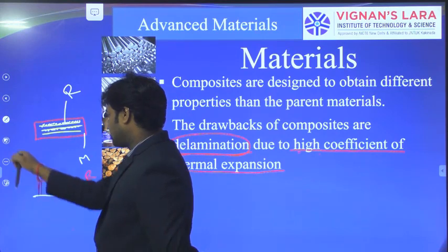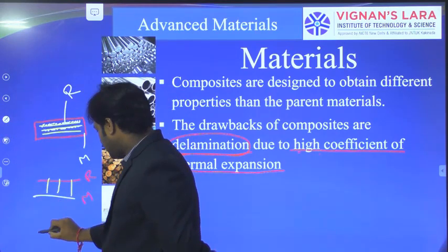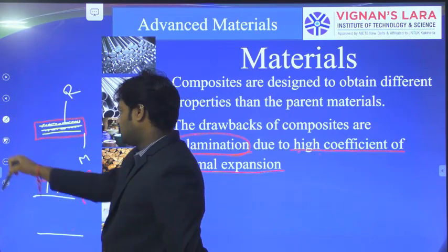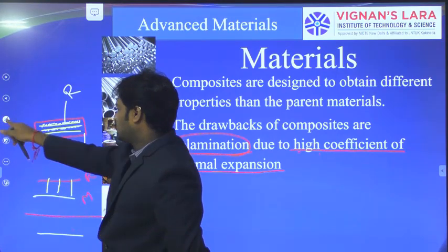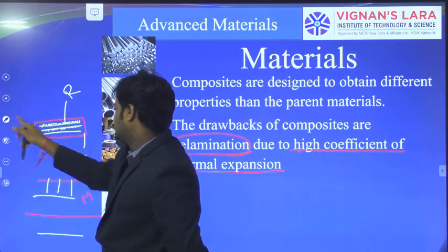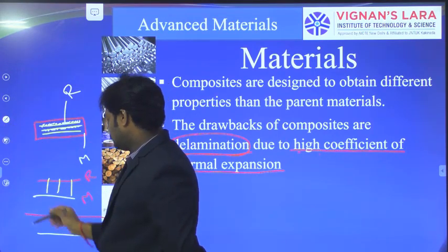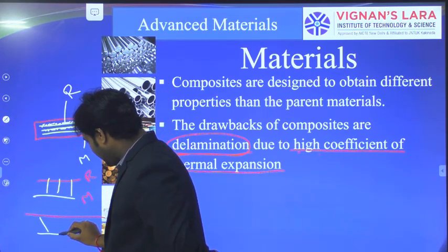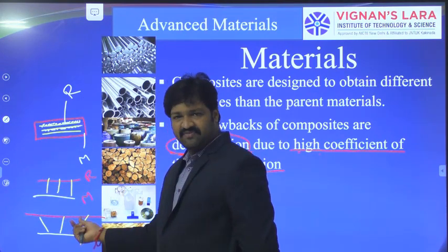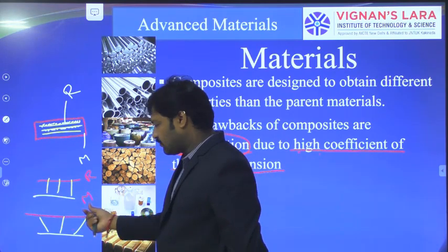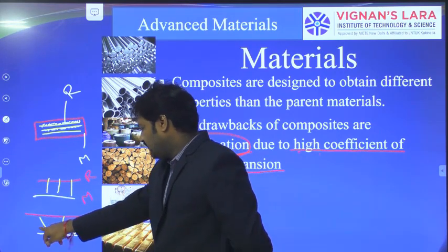In the next case, with rising temperature, the matrix will retain its original position, but the reinforcement wants to move more, so that the bonding will be damaged. So it wants to move. If the reinforcement moves further, then these bonds will be damaged.